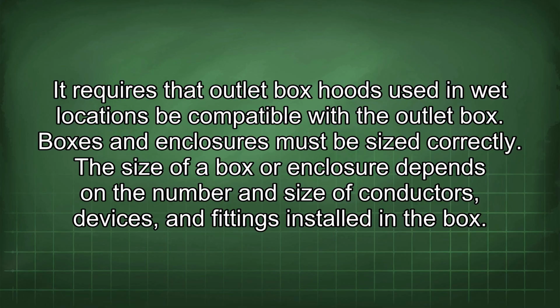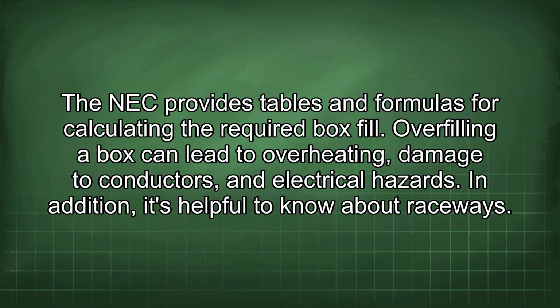Boxes and enclosures must be sized correctly. The size of a box or enclosure depends on the number and size of conductors, devices, and fittings installed in the box. The NEC provides tables and formulas for calculating the required box fill. Overfilling a box can lead to overheating, damage to conductors, and electrical hazards.